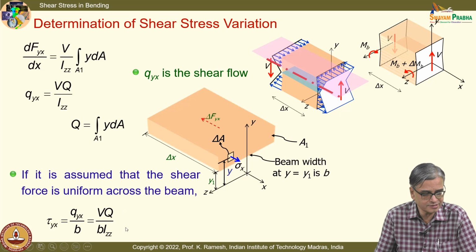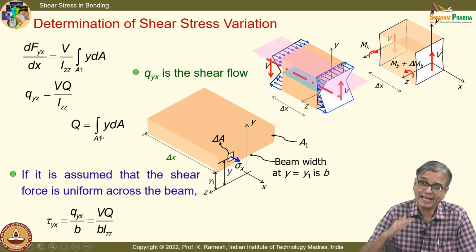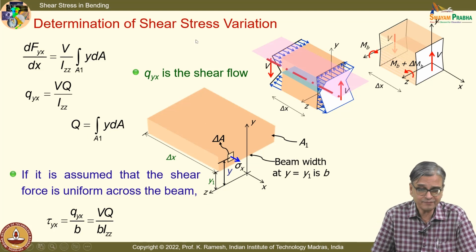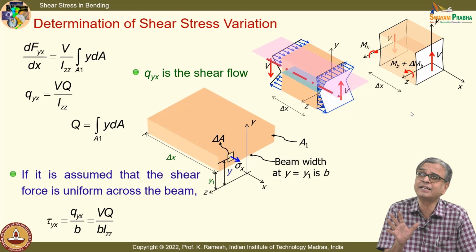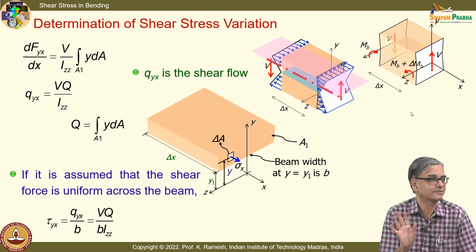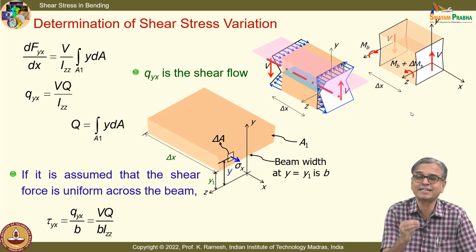So, shear stress evaluation is very subtle and you have to keep calculating Q for every cross section you look at. Here we have taken a cross section which is symmetrical about the xy plane. The edge is not straight. I have taken a small deviation in the edge just to give you an idea. We are only insisting on symmetry along a plane. The shape is immaterial in our theoretical development, but when we do the problems, we will take a rectangular cross section or an I cross section or a circular cross section, for which you can easily calculate the mathematics.